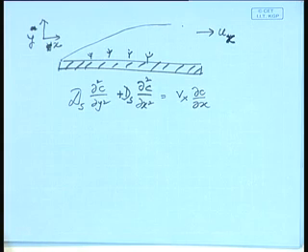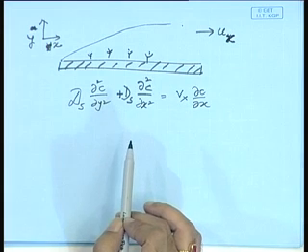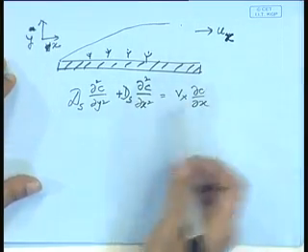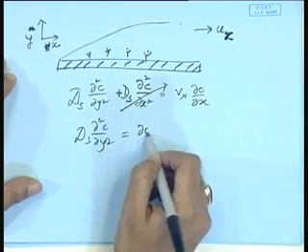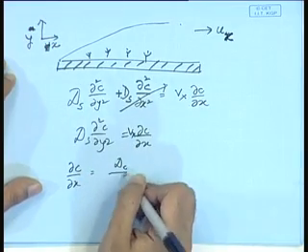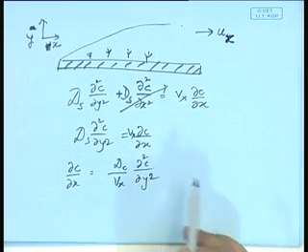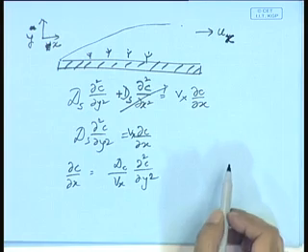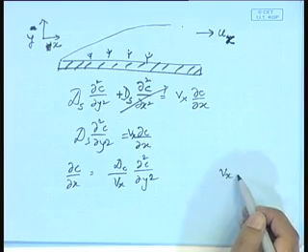You can neglect this term using scaling analysis in this direction. That's what we said initially, that when you have convection, one of the diffusion terms you can neglect. So, that's a possibility, and then if you neglect this, then d2s. So, do you know how to solve this? By assuming Vx. Yeah, but Vx in the boundary layer is going to be a function of y, right?